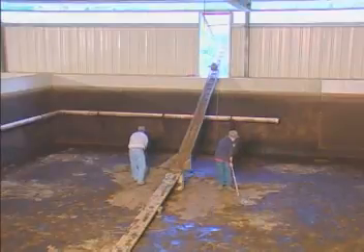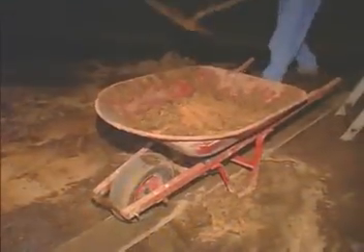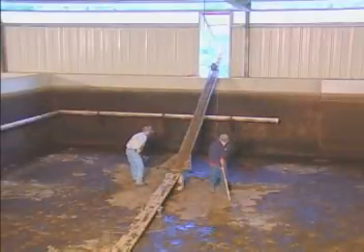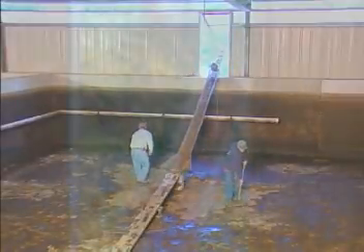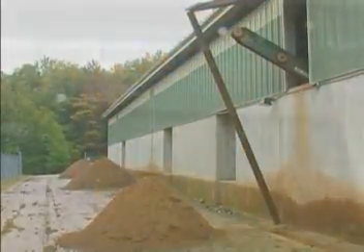As the schmutzdecke grows, the available pore spaces diminish until the water flow is restricted enough to warrant cleaning. Cleaning is done by skimming or otherwise removing the upper portion of the schmutzdecke. This material may either be disposed of or regenerated.